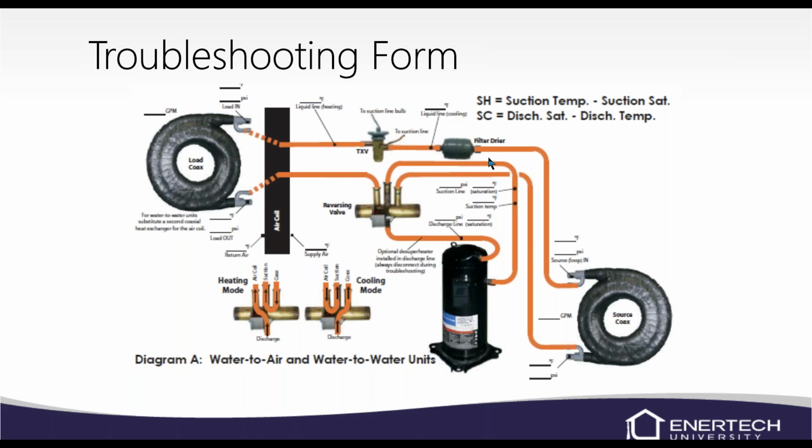Also, don't expect the unit to operate properly if you do not have airflow or you don't have water flow. The refrigerant circuit will be all jacked up. So we've got to have airflow within specs and water flow within specs. When we do heat of extraction or rejection, that'll let us know that we've got proper water flow. Airflow is usually pretty easy, you can tell if the fan's running or not if it's a packaged unit.